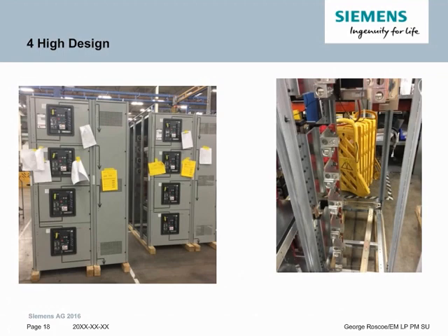And one other tip of the trade is the best way to optimize is have slightly more lugs going out the direction opposite of the through bus, because the through bus will restrict your conduit space on whatever side it is on.